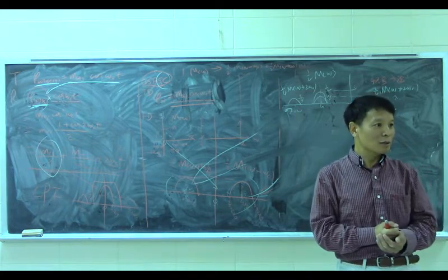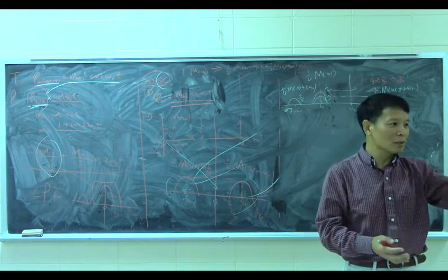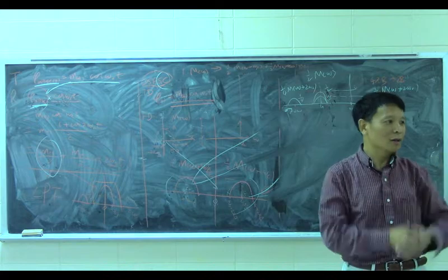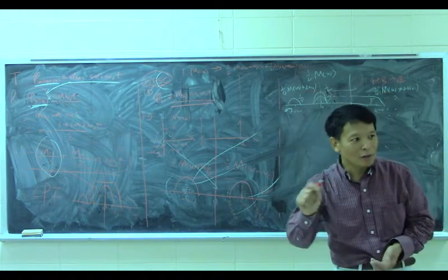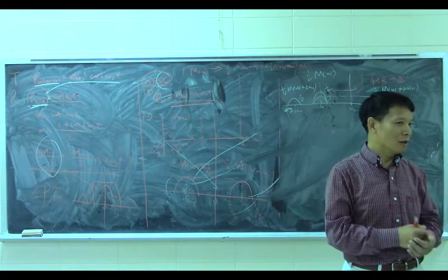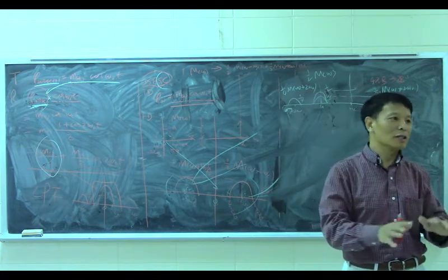What is the demodulation process? Oh, simple. You give me your received signal, I multiply by the same carrier signal again with another multiplier. Then I use a low pass filter at the end. Then I get the baseband signal. What I said here is the explanation in time.